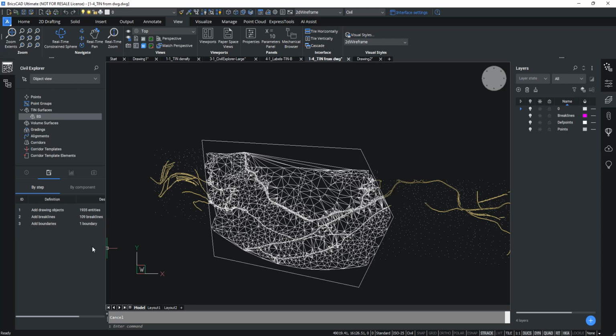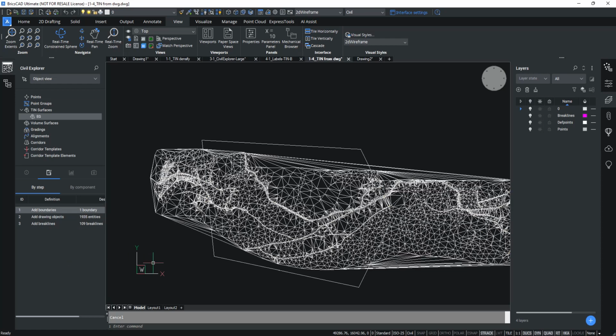And for example, a boundary really needs to go in last, because if that boundary goes in first and then we add more data, that data doesn't respect the boundary because it's already been applied. So if I gave you an example of this, pick that add boundary option and moved it up to the top, you see the boundary didn't do anything.